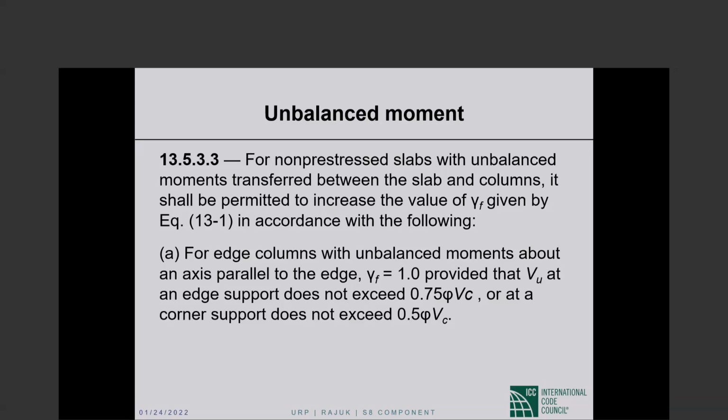This is huge flexibility because the portion that is not carried by flexure is carried by shear. And that moment transfer shear adds to shear caused by gravity. And punching shear, I have been telling you, is the problem with flat plates. So this way we get to reduce.